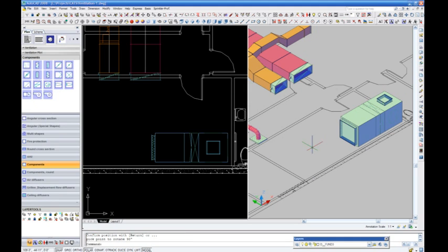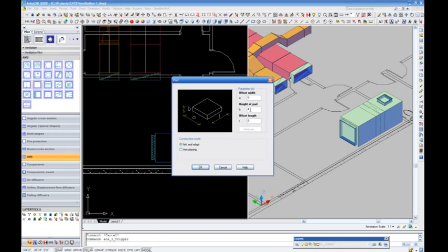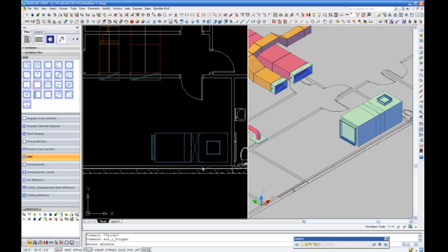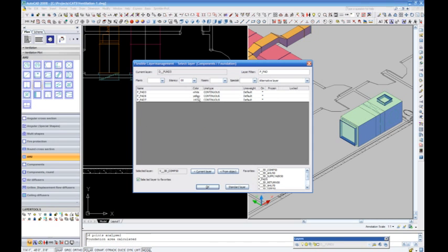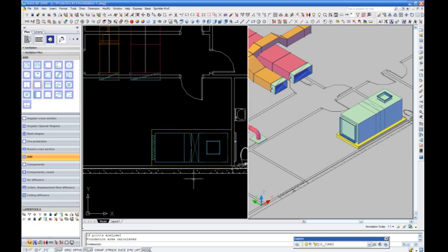Upon completion of the air handling unit design, we will design a housekeeping pad to be placed below the unit. Here we are giving a height of 6 inches. Dimensions in A and B selection are selected at 6 inches. This will add 6 inches in all directions away from the air handler. Select OK. We will highlight our unit where the pad is to be placed. After selecting the layer, the unit will be raised up 6 inches automatically, providing the space for the pad.